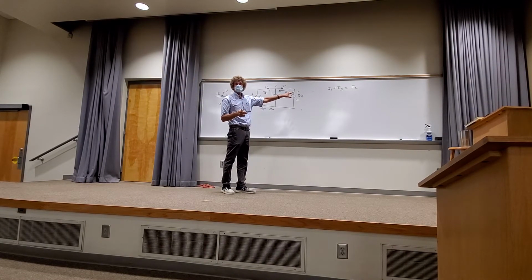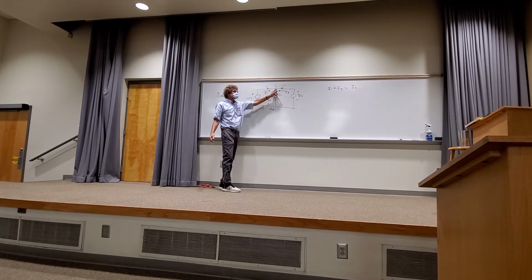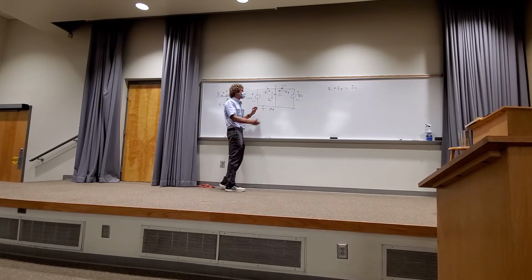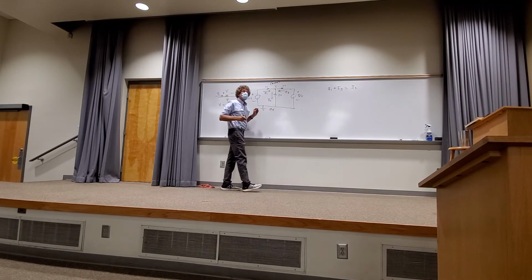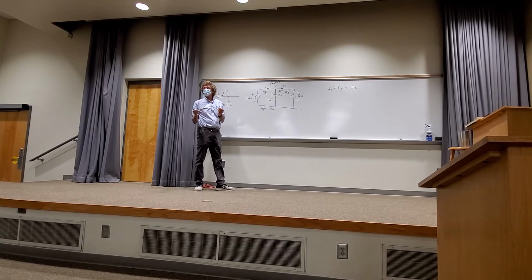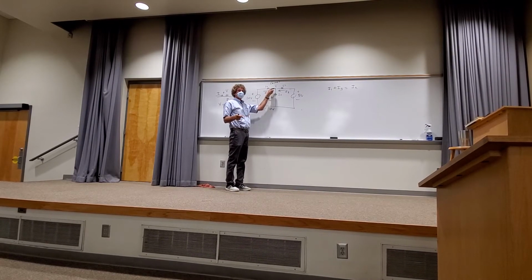Maybe it's because they make a little more sense than abstractions. All right, whatever flows in, flows out, right? Now there was only one unknown voltage. It was this at that juncture, right? And that, by the way, is called a node. A node is where there are more than two paths for current. Here I've got 1 and 1, right? But I got another one this way. There's 3, right? So there's more than one way out if you have current flowing into it. That's a junction or a node. With me, class?